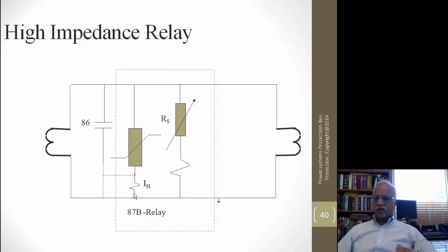For those who are trying to go and set the relay, please do refer to those for such special applications. The second requirement here is you try to use the maximum full rating of the CT by connecting it to the full winding, not the tapped.